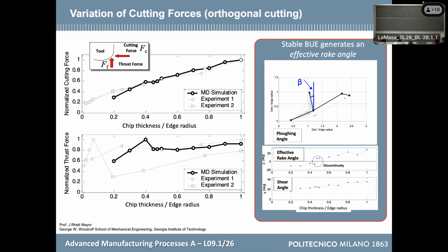But if you look at what happens to the FF, to the feed force, you see that when I am lower than 0.4, so I am not overcoming the minimum chip thickness, and we know that we are plowing, the feed force is feeling this plowing effect, and in fact it increases. As soon as I overcome the minimum chip thickness and finally I can form the chip, FF remains small, and it slightly increases, but it is not feeling the increase of the chip thickness.